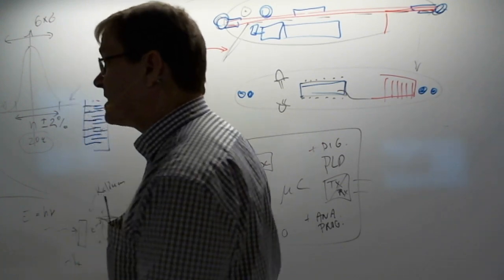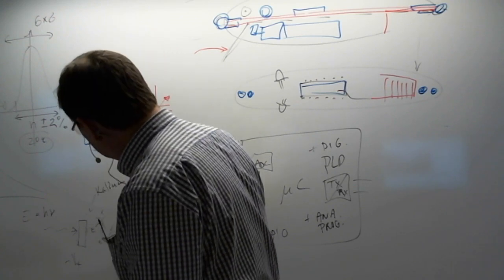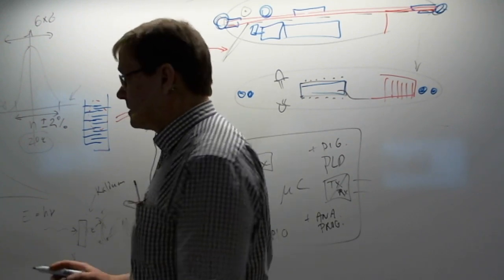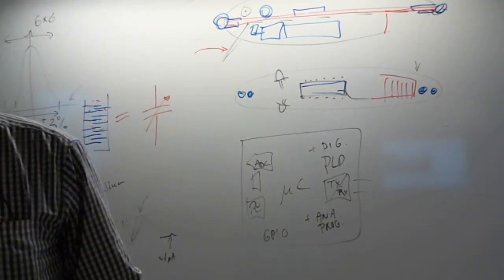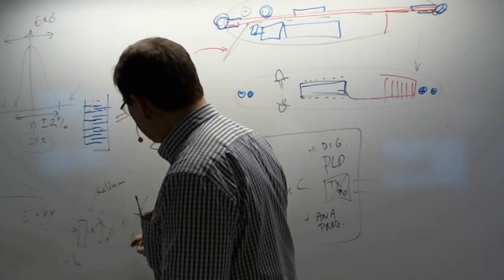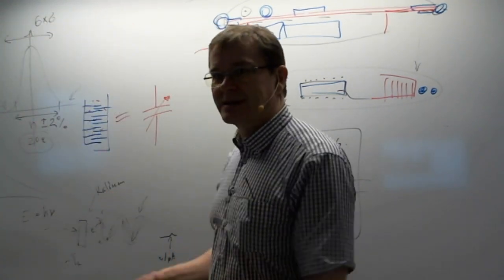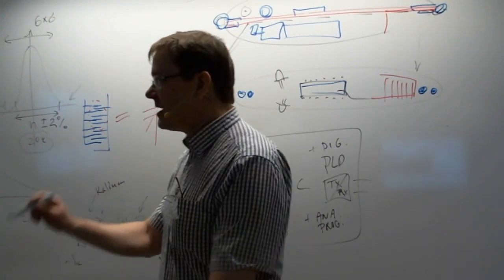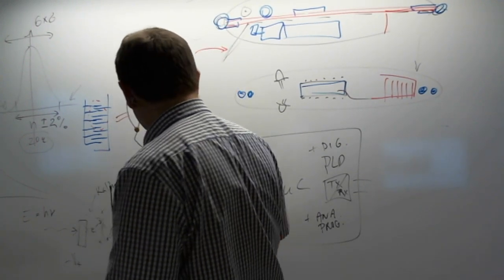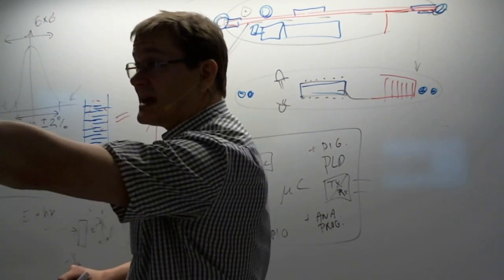this one actually has a tendency of saturating, meaning that, well, physically the later dynodes cannot give enough electrons anymore, and basically when you have higher energy here, it starts to just generate heat, and you start to heat the dynode, and it doesn't release that many electrons anymore. It starts at some point saturating. So very linear to the end, then the saturation. So it's exactly like that one there.